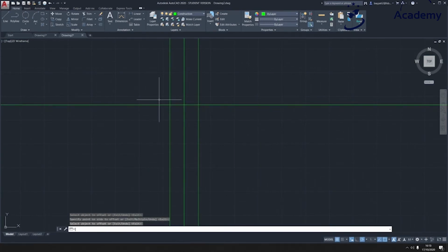I'm then going to offset 45, so I'll go to the offset tool again, this time type 45, click the center line again and offset on the left, click the center line and offset on the right. So we've now got all our vertical lines that we need. And after we've got all our vertical lines, we can now do the horizontal ones.